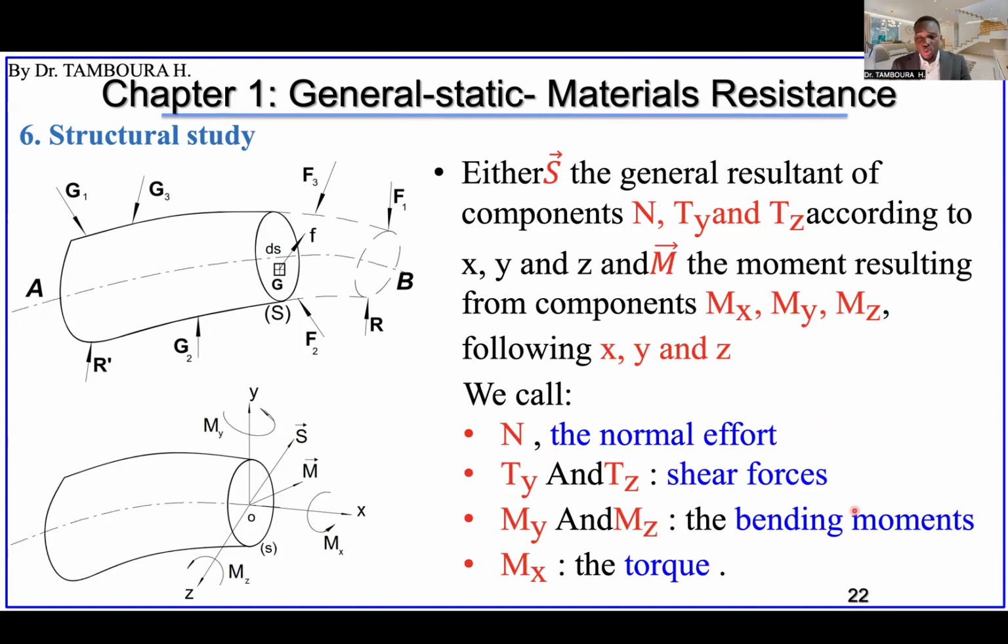All the forces that are parallel to that axis are perpendicular to your section. The forces perpendicular to your section are normal forces. And the moment turning around the axis normal to your section is the torque. All the other moments are bending moments.